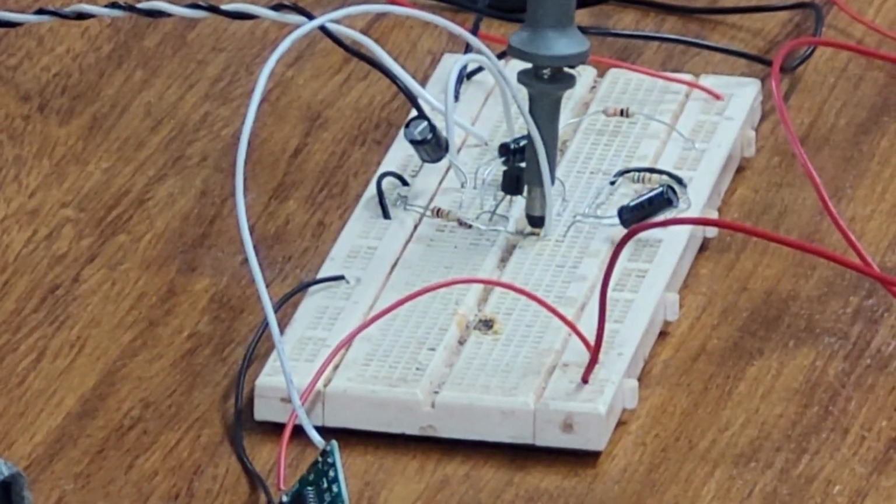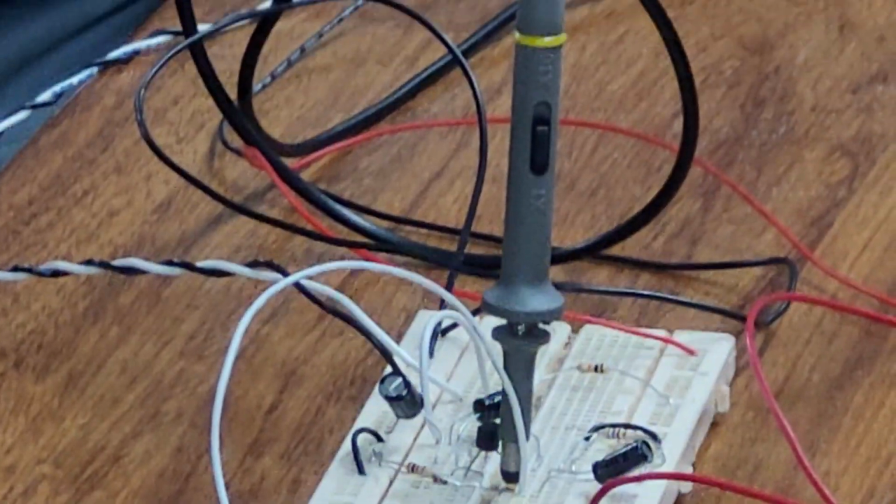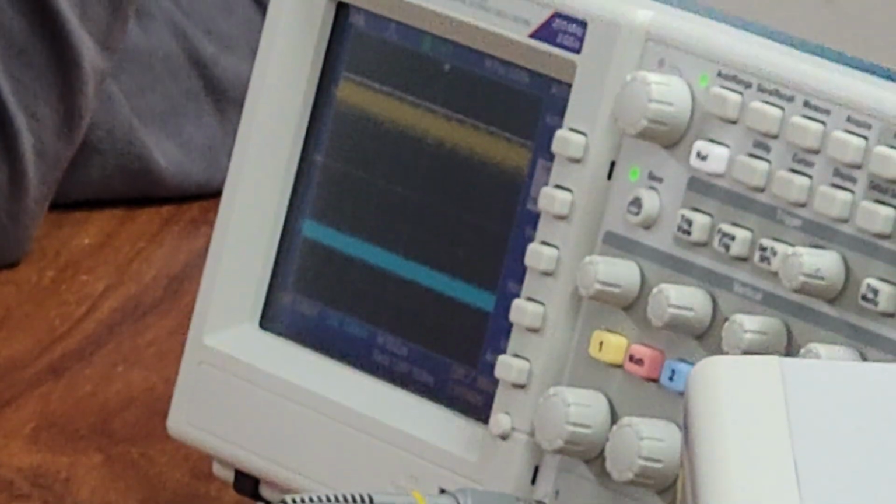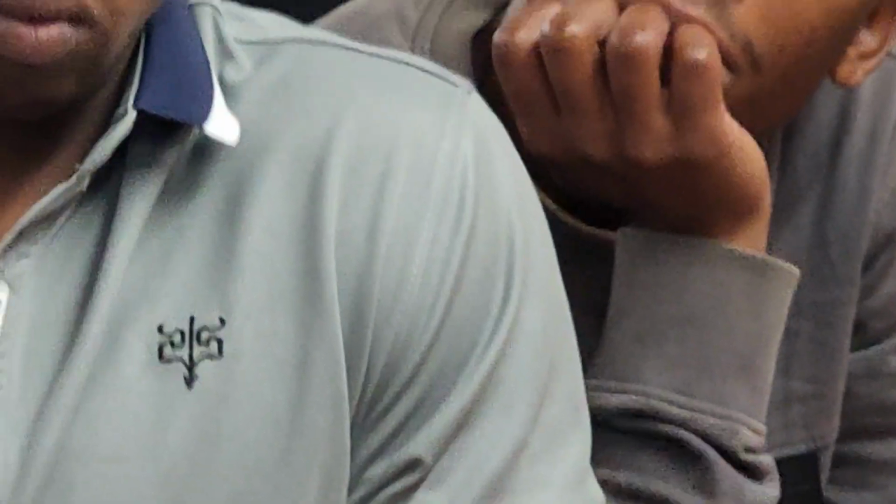And instead of using the microphone as the input, I can connect the output of that diode detector here, and immediately you will actually hear the hiss that we associate with AM radio, like that. And when you tune it under the right conditions, you should be able to pick up a radio signal, a radio station broadcasting in AM, play through this very speaker. Okay, so this is not just a textbook or theoretical thing. There it is in front of you.